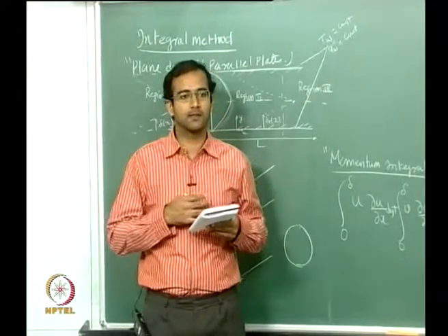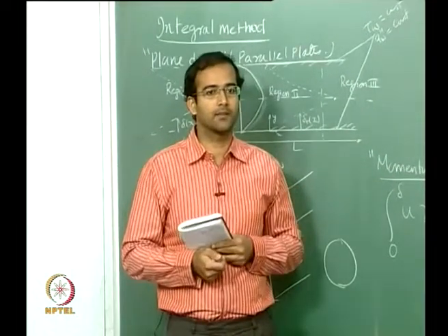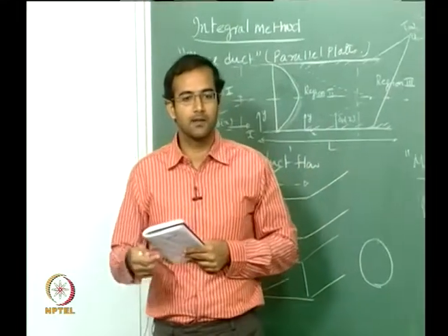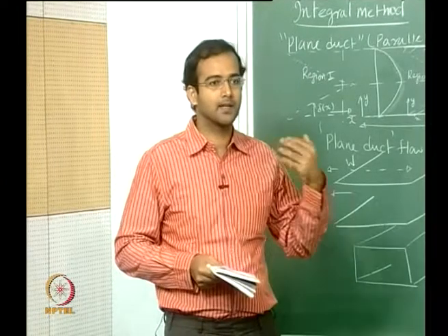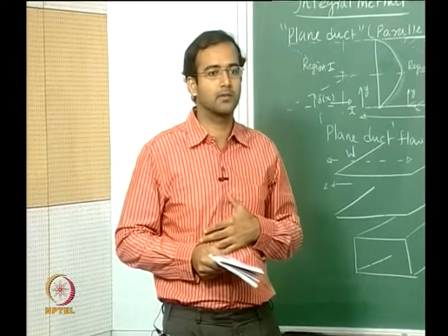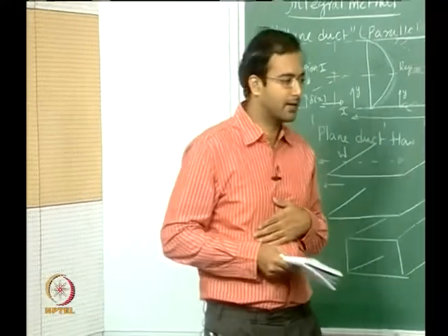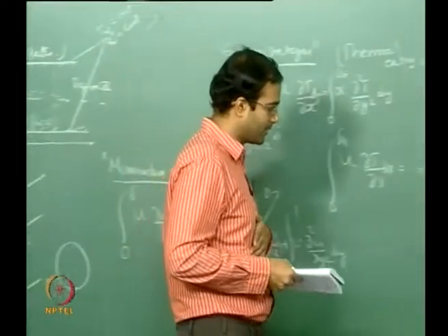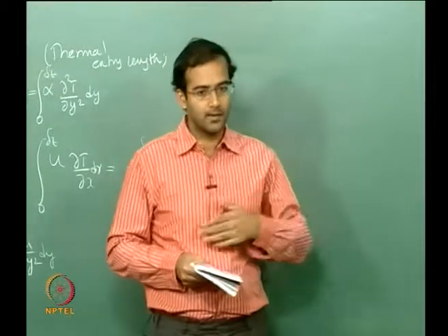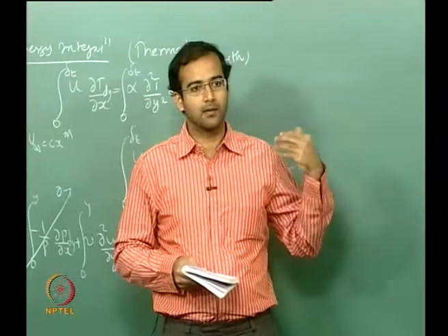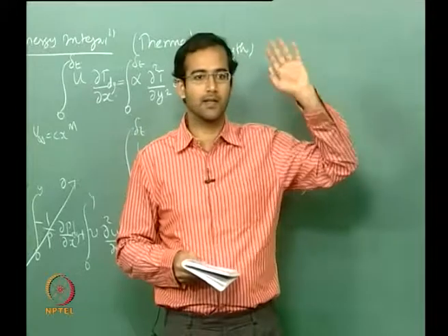It is not as wide as in external flows, where you used it for almost all the problems where you had a similarity solution. You replace that with an approximate solution, and in fact even more than that for cases where you had an unheated starting length, for example. There you cannot use the solution from similarity variables. The cases with a pressure gradient were much simpler, and also the case where you had a non-uniform wall temperature or wall heat flux, a linear variation or any other variation.